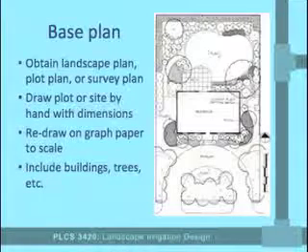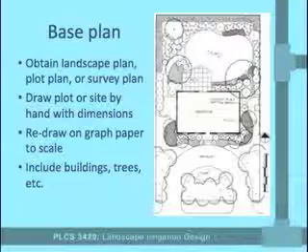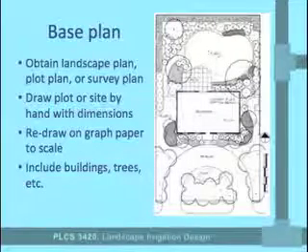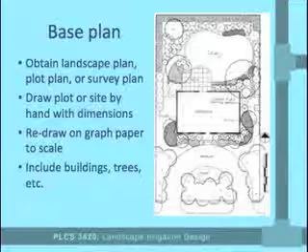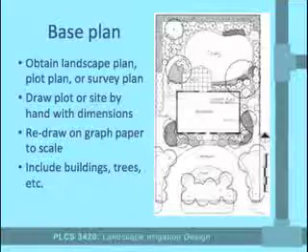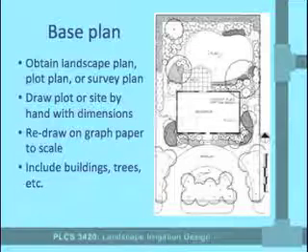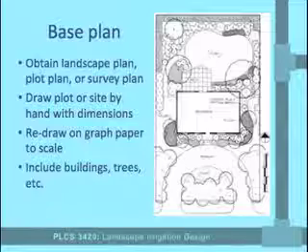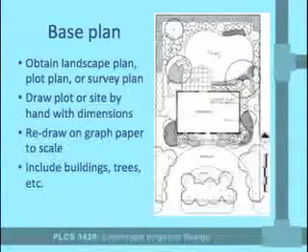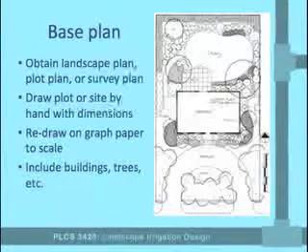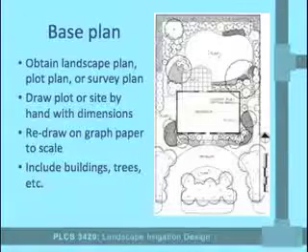On the other hand, if you can't obtain some kind of an existing plan, a scale drawing on graph paper is a good alternative, especially for really small sites. The shape of the area should be drawn on the base plan with all the sides and dimensions accurately measured, and then you want to take additional measurements to assist in drawing any curves and odd angled borders. And your landscape planting design, I'd say, is trending a lot toward those more oddly shaped areas.